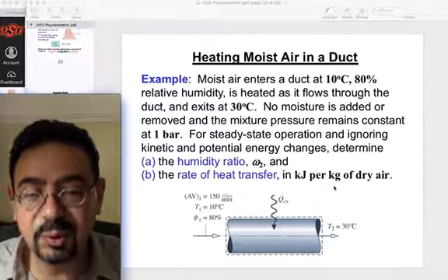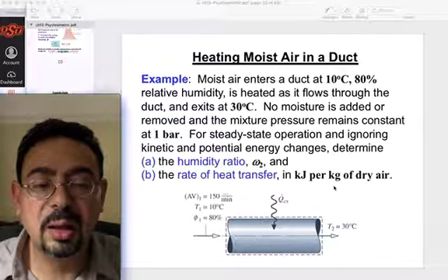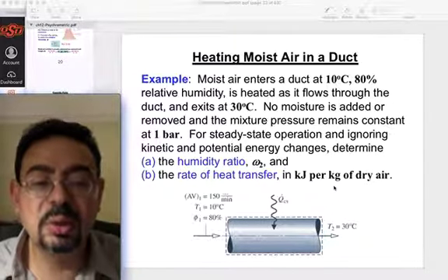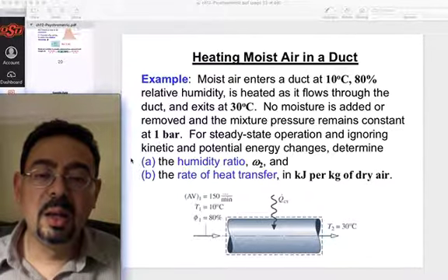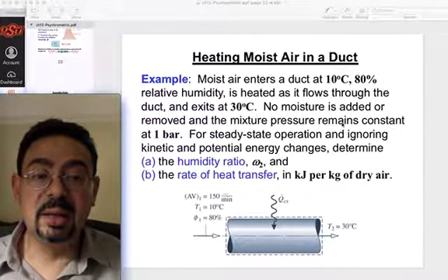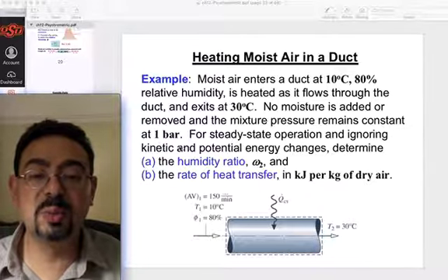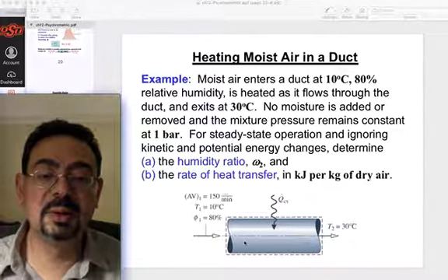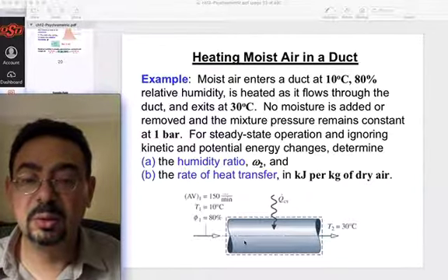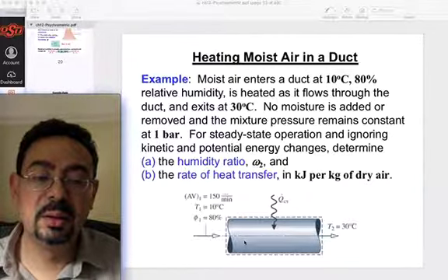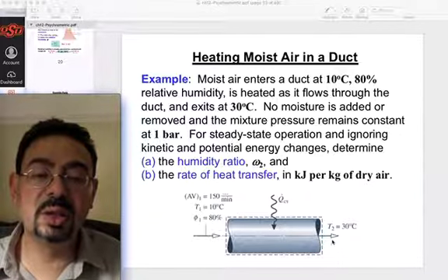So you have to use the continuity equation. All right. So let's think about part one first. By the way, the pressure is constant. He said that the mixture remains at constant pressure, 1 bar. So 1 bar, 1 bar, right? 1 bar is 10 to the power 5 Pascal. Okay, so this is heat addition at constant pressure.